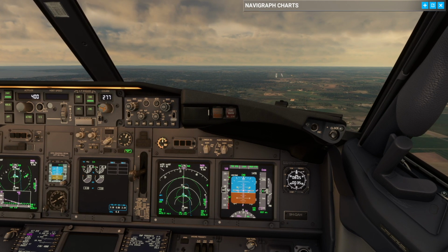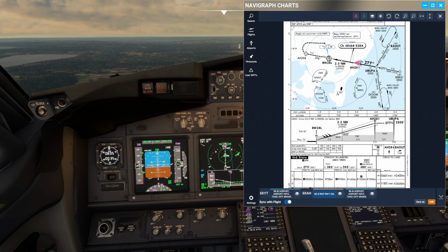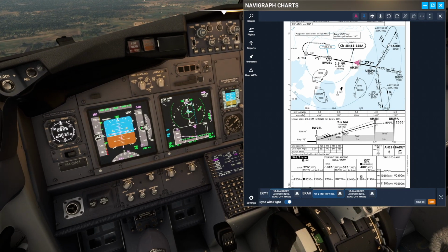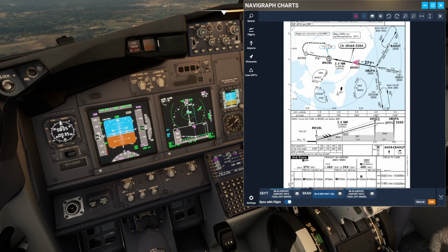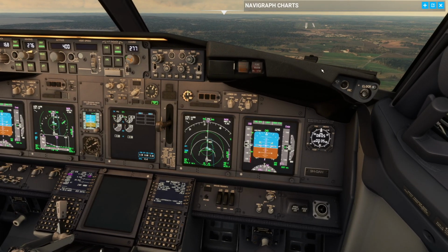We want to reset the missed approach altitude. Whereas for the pilot monitoring, we should reference distance to 28 left, 5 miles, 1720, 4 miles, 1405. So next time 4 miles is going to be 1405. State that to the pilot flying, and then we can call if we're on profile.